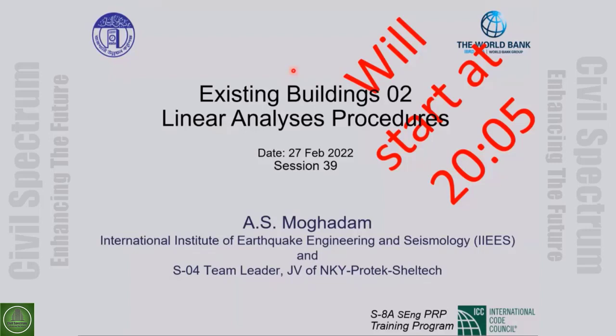But for extraordinary loading such as blast, and in our case earthquake, where the level of load is much more than the other loads, we accept damage. There is no way to design economically for such large forces. So we accept damage and we design for ductility.